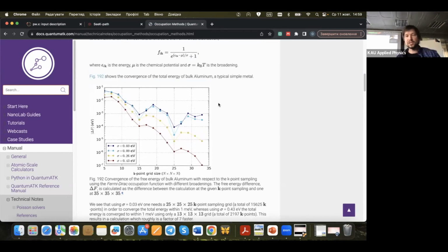For very, very good calculations, we also had to converge this degauss parameter. It's another parameter we had to converge, but for our calculations, I think that we shouldn't do it, because the accuracy of our calculations is not so good, and we can use it just rather small, adequately small for insulators, and higher, like 0.2, for metals, and it will be great.